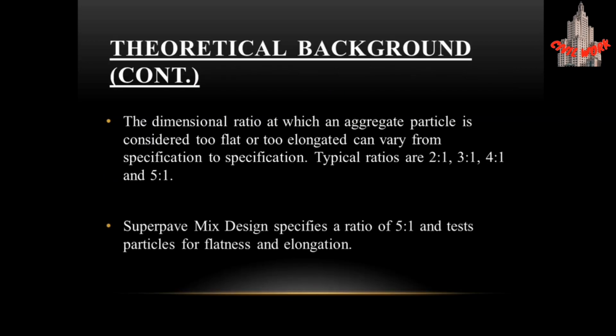The dimensional ratio at which an aggregate particle is considered too flat or too elongated can vary from specification to specification. Typical ratios are 2:1, 3:1, 4:1 and 5:1. Superpave mix design specifies a ratio of 5:1 for testing particles for flatness and elongation.